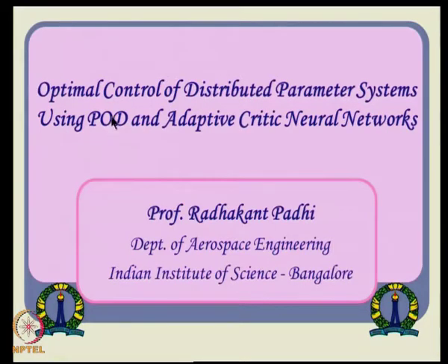But on the other hand, this POD is not a miracle technique either actually. Now, if you ask me, the proper orthogonal decomposition ideas appear heavily in homogeneous system dynamic solutions, and that is very much justified, because the solution nature is not changing. There is no control input, so the solution behavior does not depend on control input; there is no feedback there actually. That means every time you solve it from a different initial condition, the solution nature is sort of unique, depending on the system dynamics. So, those problems are okay.